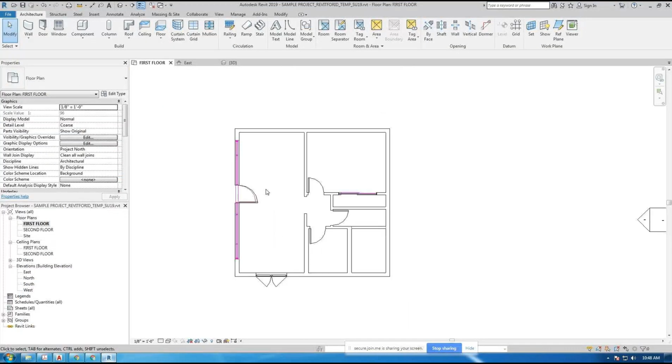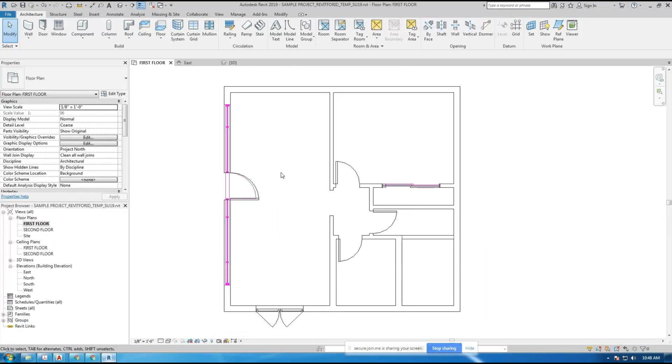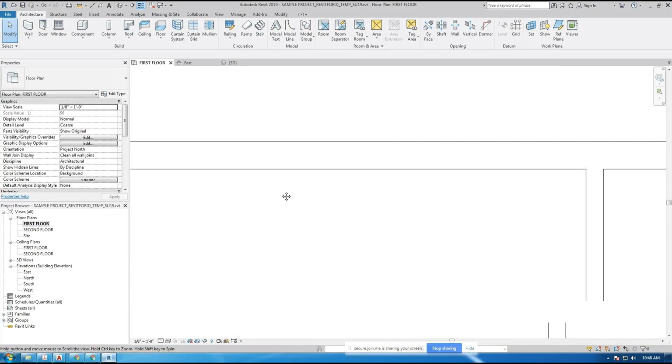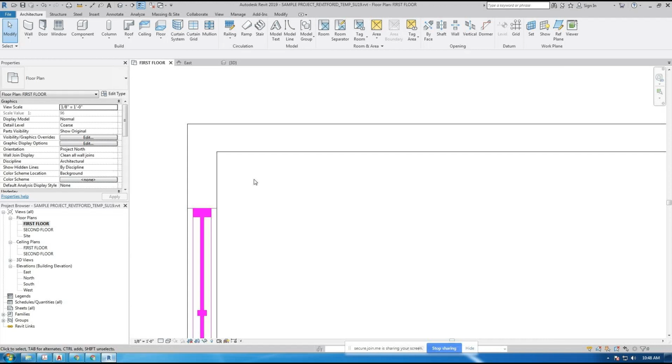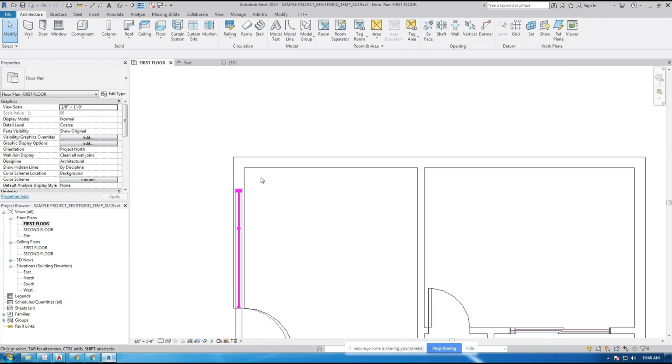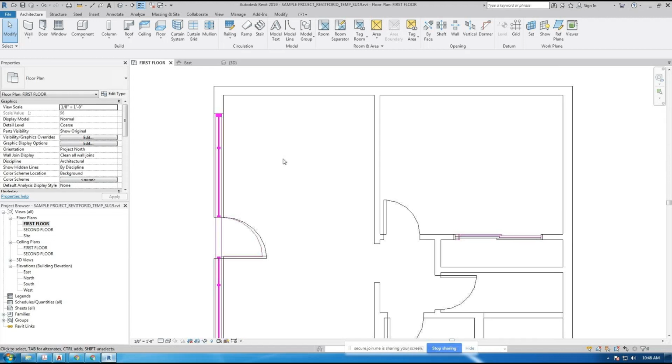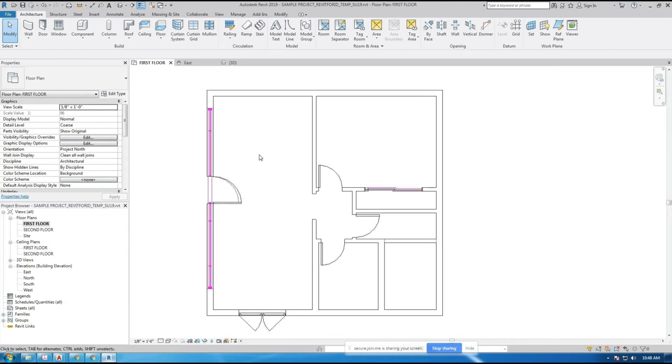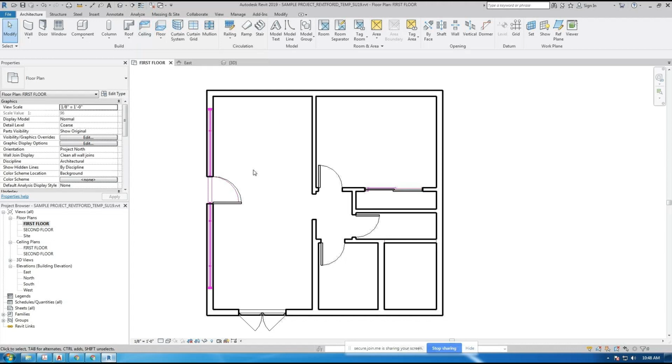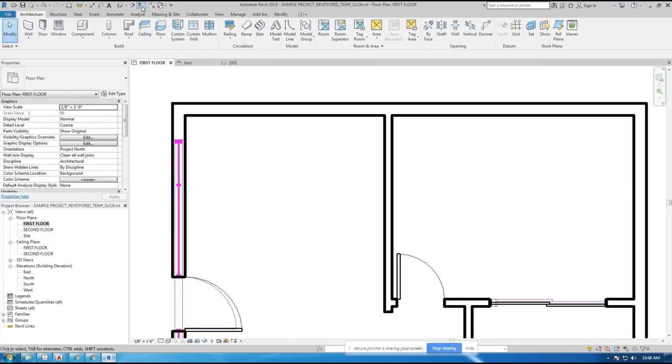Another quick question. The tools in Revit are showing the walls here, kind of like AutoCAD. Here, the walls are kind of thin. There is a way to launch line weights in Revit, so you can see a preview of how they will print out. Sometimes it's useful to see it in Revit with thicker lines. So up at the upper part of the screen here, next to this 3D icon, there's a little command called TL, or thin lines. If I click on that, notice how my lines get thicker. So typing TL switches and shows you the line weights.